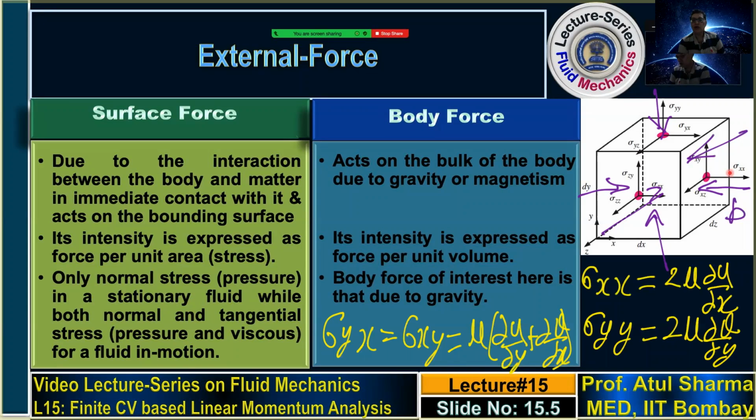Okay. So for a 2D case, I am showing you that these viscous stresses are directly proportional to the viscosity, and they are a function of velocity gradients, where u is the velocity in the horizontal or x direction, and v is the velocity in the vertical, y direction.